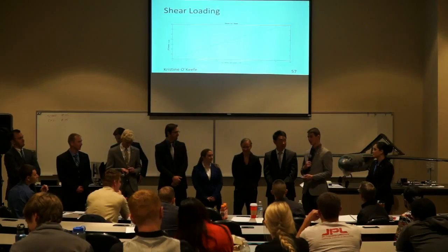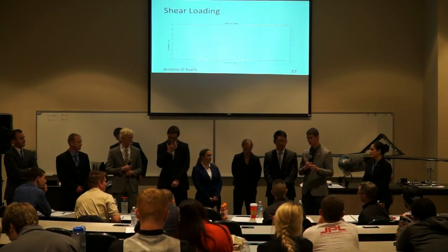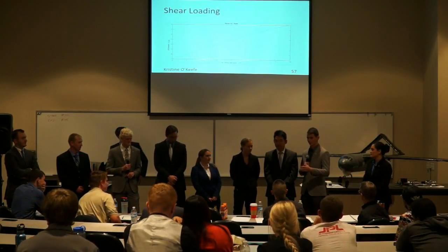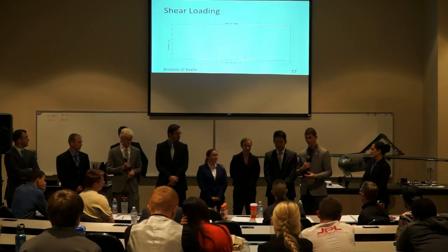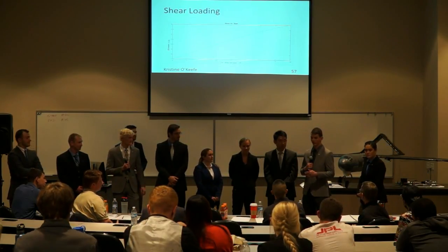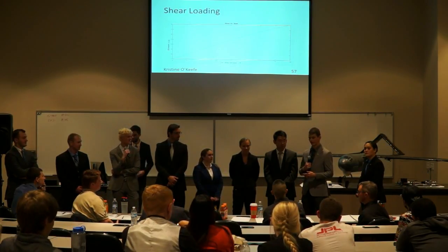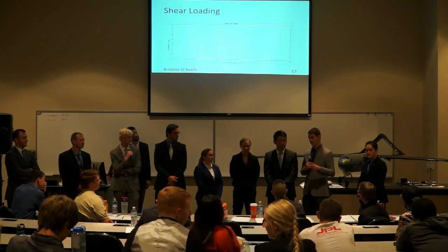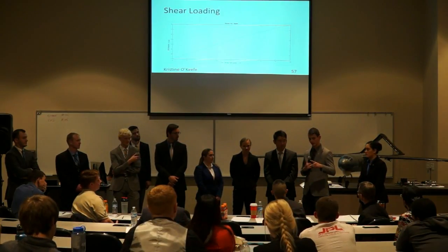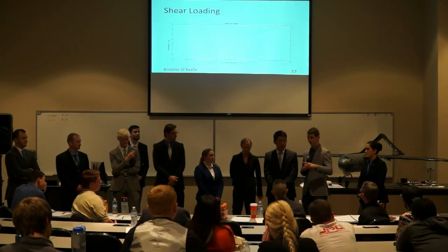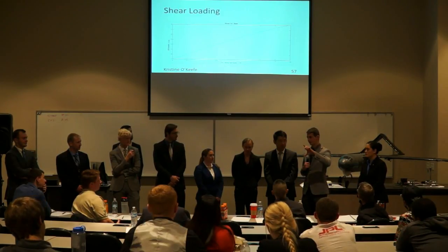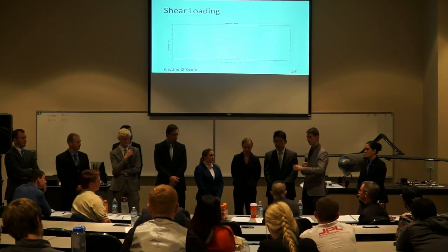So originally our drag data, well, drag's supposed to be 0.0 something, 0.0345. Originally we observed it to be 0.5, 0.6, 0.7, and that was because the tare on the drag was about 0.5, 0.6, 0.7, since it had a giant balance sticking out into the free stream and caused a lot of drag.